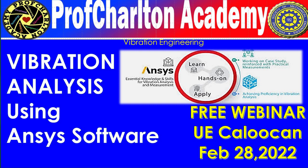Now we can solve the analysis. Before solving, let me also request some results. I'm going to insert deformation, because I want to see the total deflection of the material. Now I can solve the analysis. So right click on the solution, solve. Okay, the solution has been solved, and you can see the deflection. Deflection is 0.06 mm.